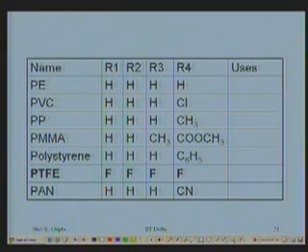less than 0.5%. That is of the order of 0.005 coefficient of friction, or between 0.005 and 0.01. That's the coefficient of friction we have. It's very small. In other words, as compared to other metallic bearings where the coefficient of friction could be high, in the range of 10 to 30%, this is a much better one.